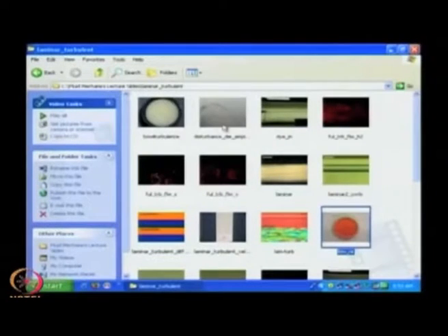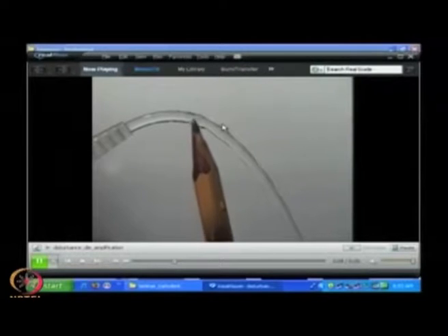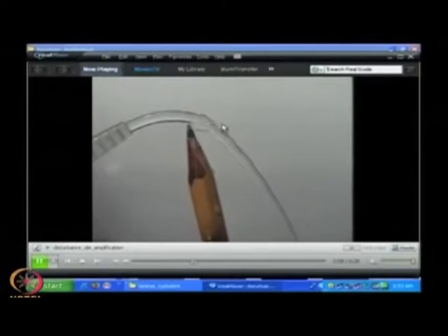Now let us look into a different case. Again, this is a water outlet. Now you see with a pencil the flow in the water is disturbed, and after it is disturbed, see, it has no influence. Once the pencil is withdrawn, you see that it is just like it was. Now look at another situation. Here a perturbation is created by an arbitrary rotation, and if you look at the motion of the colored balls, it is totally, apparently erratic.